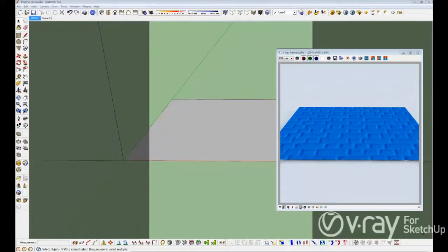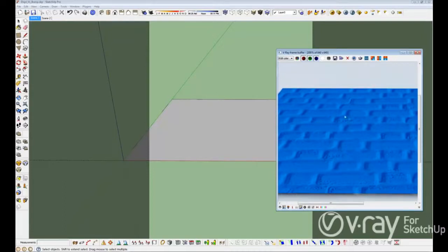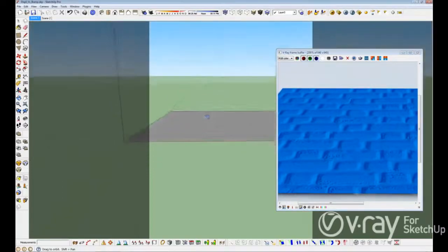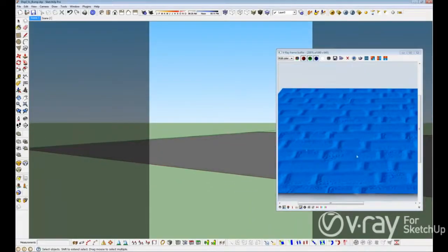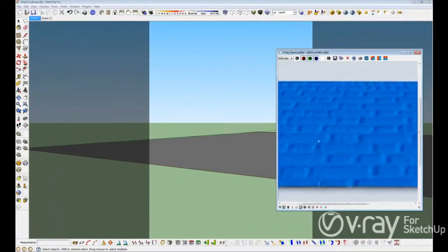Bump mapping is a shading effect that is used to simulate the subtle bumps on the surfaces of geometry. The bump map effect does not deform the geometry. Here we have a simple plane. The goal is to add detail to the geometry with the bump map effect. This will eliminate the need to model the details.